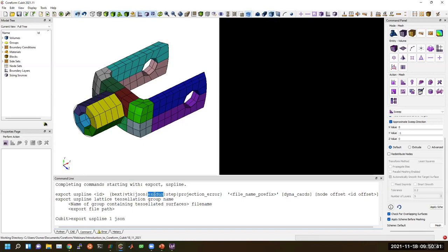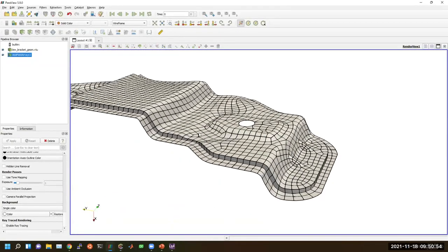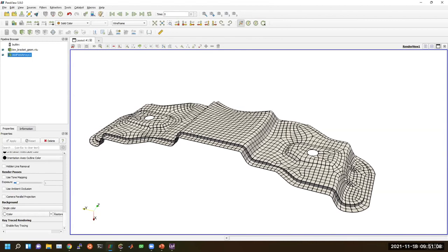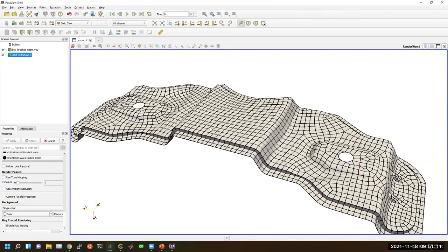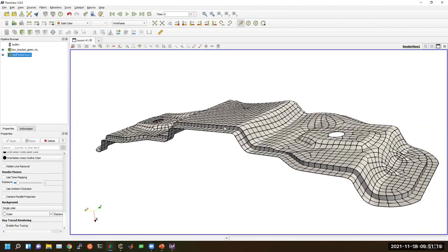Yeah, the preferred post-processor right now is ParaView, because we've added support for IGA there. And is that available in the standard ParaView download, Greg? Yeah, so the way that we render U-splines here is they have a new, in ParaView 5.8 at least, but certainly in 5.9 or newer, an unstructured cell type, which allows us to render Bezier elements, which are what each of these are. These are each Bezier cells natively in ParaView, but the control points aren't in this format.